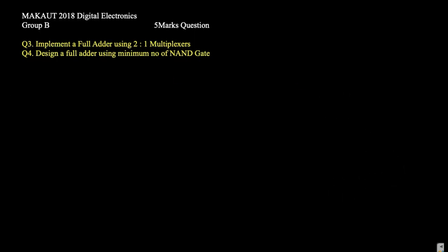Now the full adder circuit is the logical circuit that adds three single bit numbers. That is, the full adder is able to add single bit numbers. That means we have 1 0 0 and 1 1 0. So 0 plus 0 is equal to 0, 0 plus 1 is equal to 1, no carry, but 1 plus 1 is equal to 0, and there is a carry 1. It means that for this we need the previous carry for addition. Okay, now consider the expression elaborately.